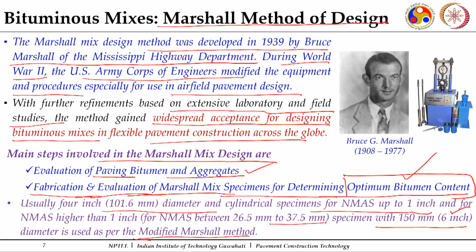And that particular mix design method, when modified especially for 6-inch specimens, is known as modified Marshall method of mix design, and the one which is practiced with 4-inch specimens is the standard Marshall method of mix design. There are certain differences, especially like the hammer weight, the mold sizes, and then the requirements which are to be met on the parameters which are obtained out of it.